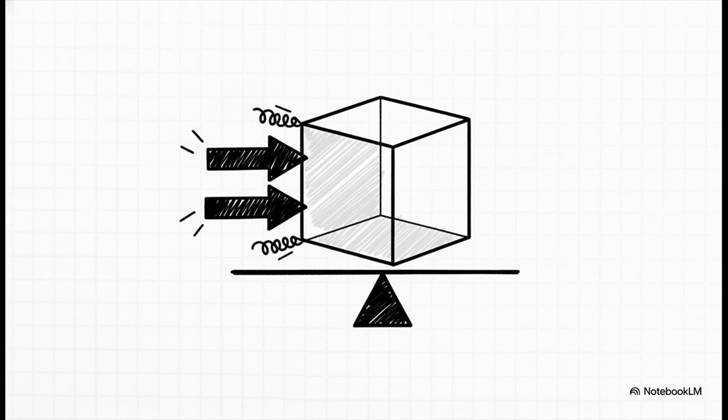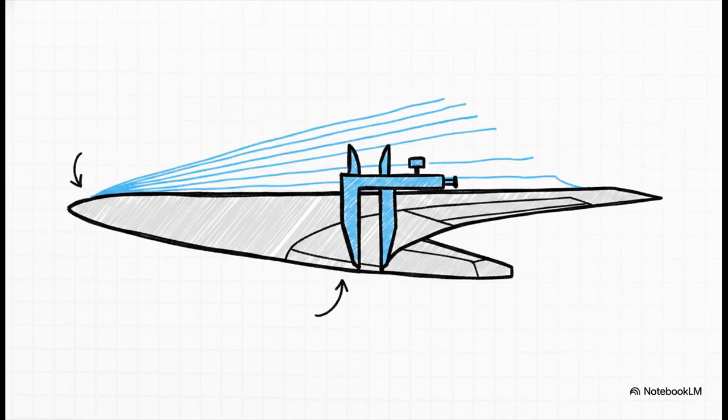So the really crucial point here is understanding exactly what physical forces are fighting each other inside that box. Fundamentally, this equation just balances the viscous shear forces, the physical drag slowing the fluid down on the bottom face, against the pressure forces pushing the fluid forward. And by solving that delicate balance of forces, we arrive at this remarkably elegant equation for the thickness of the boundary layer, which we denote with the Greek letter delta.